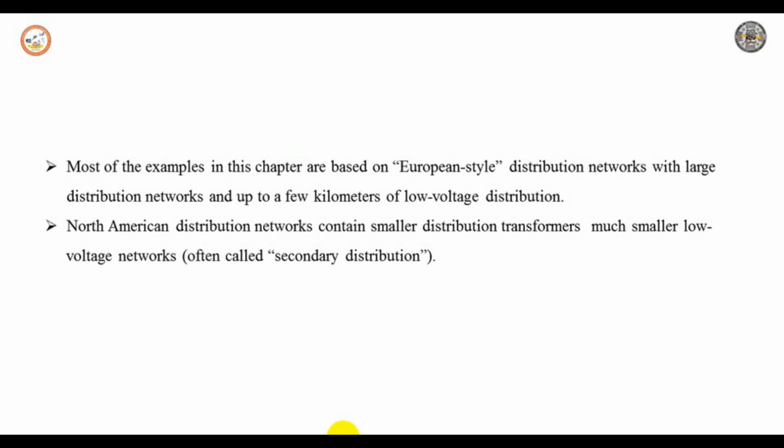There is an article published in the Indian Electrical Engineer Journal. The situation can be addressed by operating the load tap changers in power transformers at 66/11 kV and 33/11 kV substations. By providing a combination of switched capacitors and automatic voltage regulators on 11 kV, we can mitigate this risk.